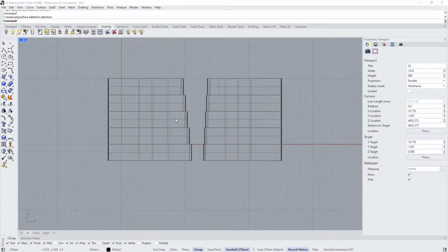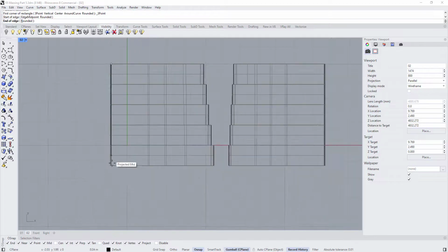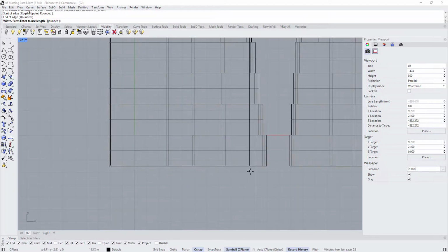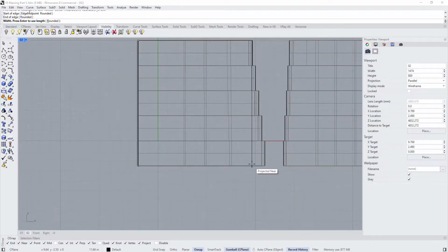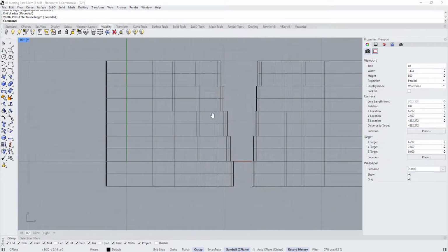Okay, now we want to trim some parts from this shape, so we are going to use Boolean intersection for this. So open the project so it doesn't snap to any point in the 3D, and choose 3-point rectangle. Let's draw maybe a rectangle, something like this. Press tab to fix the movement in this direction and snap to this point.